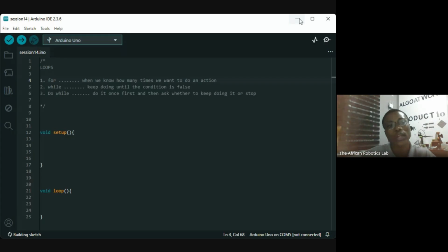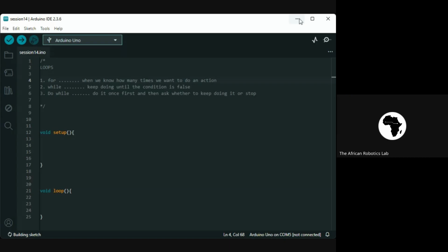So in that particular application, if you do not want to waste so much power on your sensors, and you want the system to just get the sensory data just 5 times, or just 3 times, you can use the for loop, right? So that's so simple. All right, let's go into it. Let's go off video and then let's go into Arduino IDE.